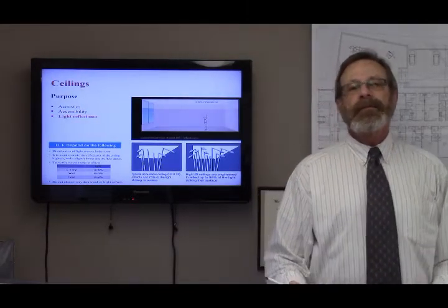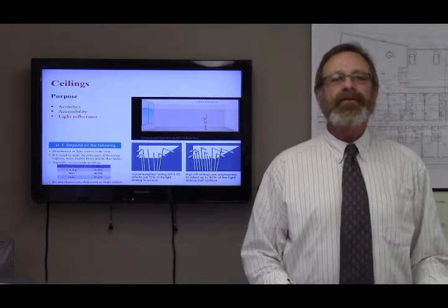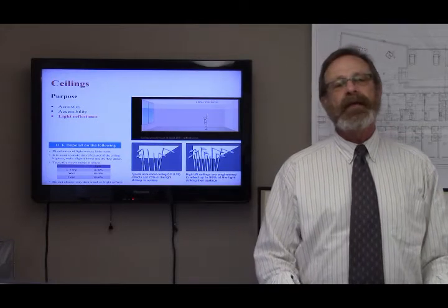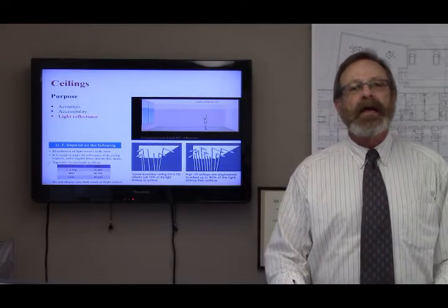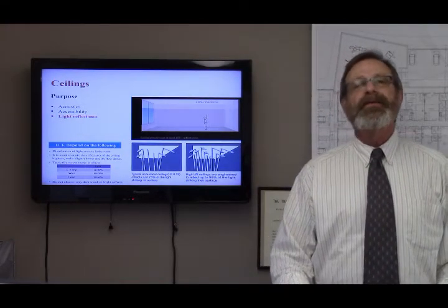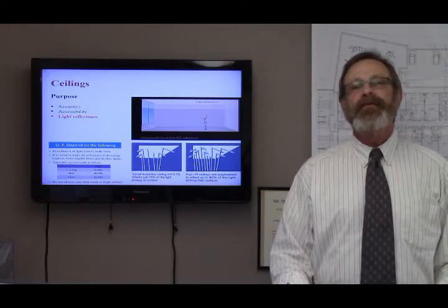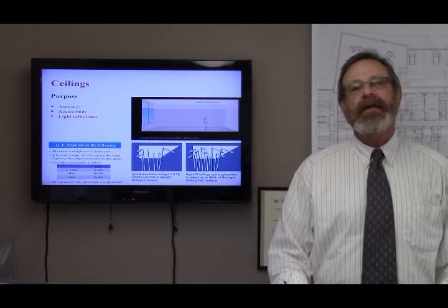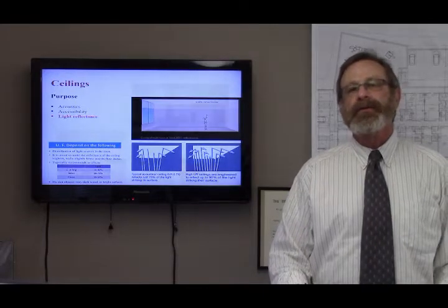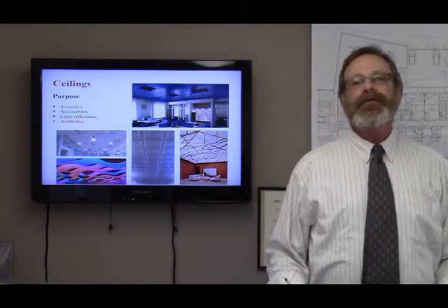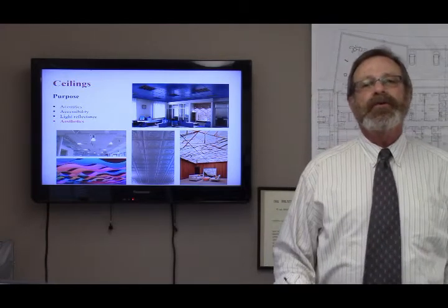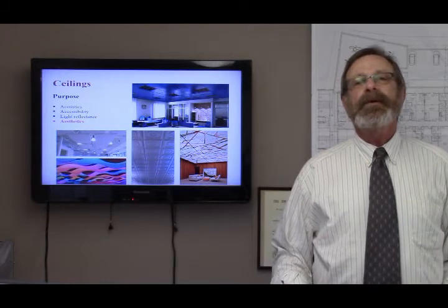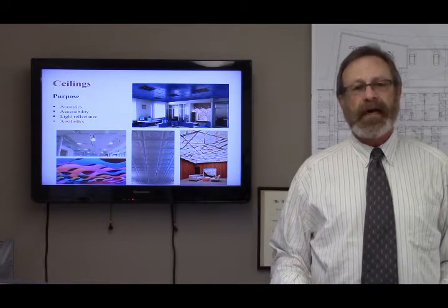It is our responsibility to identify the spaces and the tasks within the space and to verify the number of foot candles required for the task, as well as to analyze the daylight in the space to determine the need for artificial lighting. Reflectance values from the ceiling influence these calculations. In addition to standard flat ceilings, designers may want to use the ceiling as a design feature to create a sense of movement or otherwise reinforce the design.